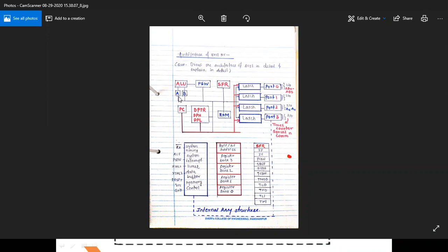How can you write about the A register? A stands for accumulator. It is 8-bit long. In any operation, this register contains the first operand. Now see, if you want to perform 5 plus 3, you can say 5 or 3 as well. Means you can say 5 into accumulator or 3 into accumulator. But if you want to perform 5 minus 3, then your 5 should be in the A register. That's why you have to use the word first data.